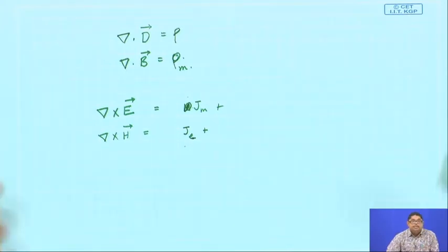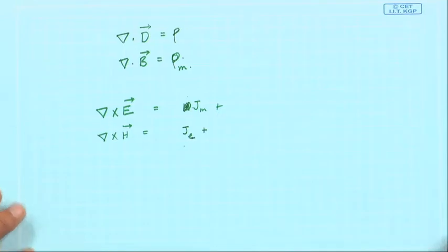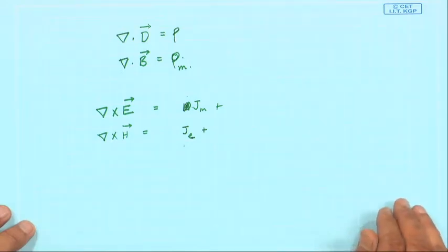So, also before going to this actual discussion of this equivalence principle, I will say what is the closed surface. A closed surface, for this equivalence principle, means a surface which encloses the sources, and they are taken to coincide with the conducting part of the structure or antenna, because then our integration domain gets very much reduced if we can include in the surface the conducting boundaries, because we know that in conducting zones various field things get cancelled.